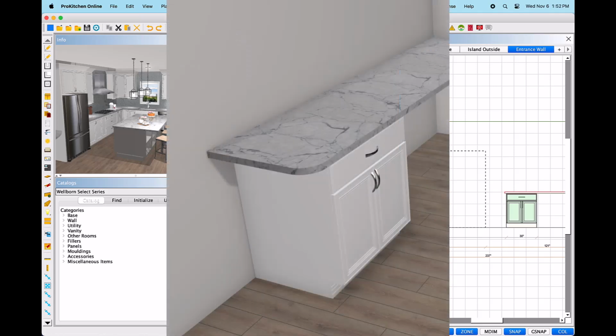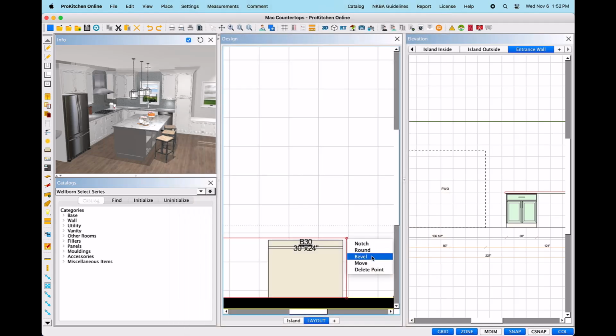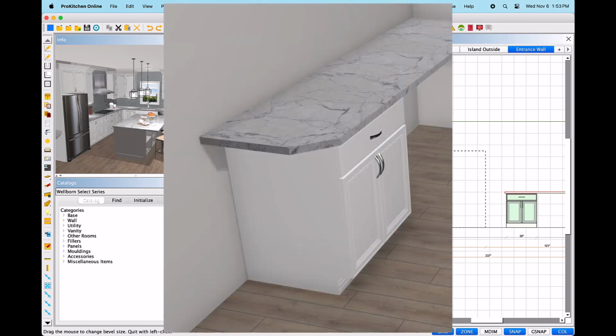Back in the additional right-click toolbox for a point, you will find Bevel. Again, once selected, you may only make this edit toward the interior of the countertop. This time, an angled line will appear that will essentially cut the corner off and provide a smooth, straight edge in its place. Once the beveled edge is in the desired location, left-click to secure. There will then be an additional 2 points and a single line in which you may select and continue creating edits.